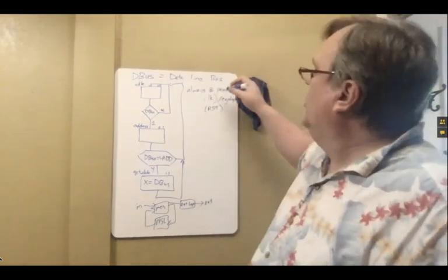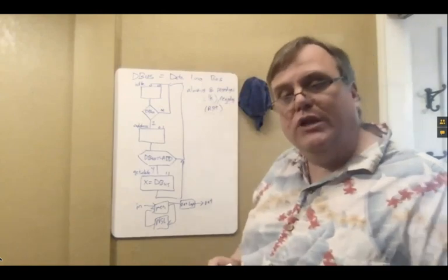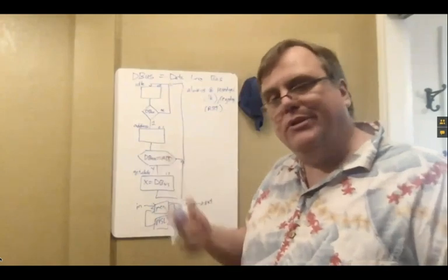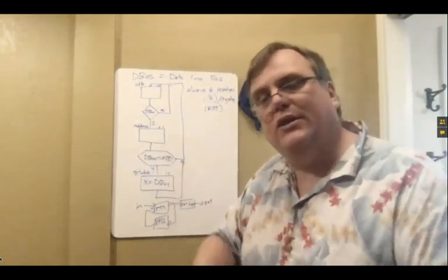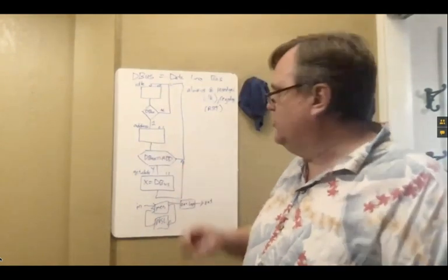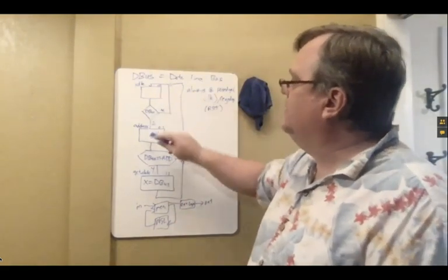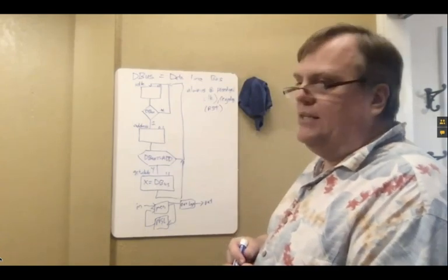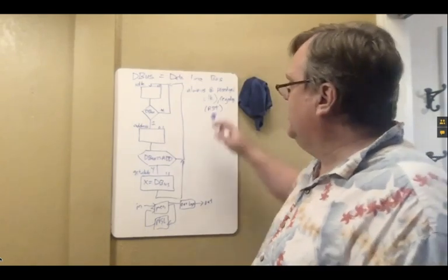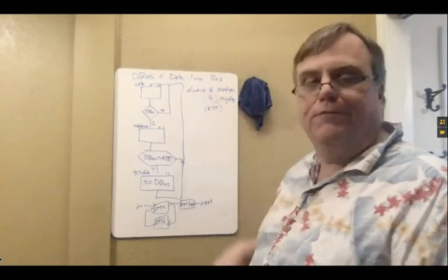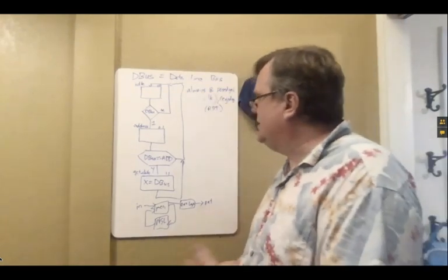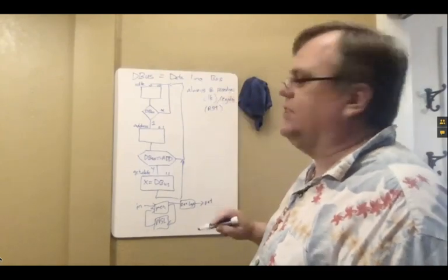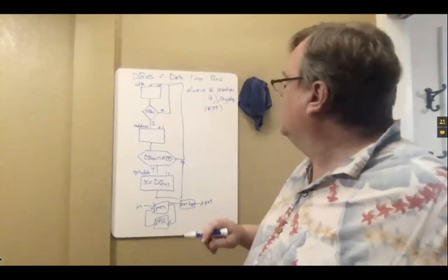So I would have to add, obviously, clock and reset as single bit wires coming in as inputs. I should have thought of it when I was doing it. But at this point, I would go up and modify the module to allow my clock and reset to come in. If you're doing SystemVerilog, you would have always_ff for flip-flop, which specifies, yes, I really do want memory. It will be inferred from the positive edge clock for regular Verilog.